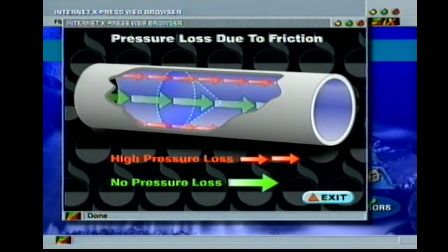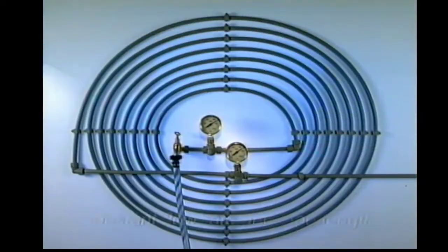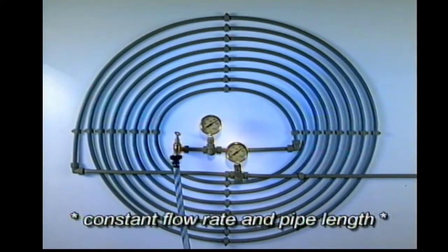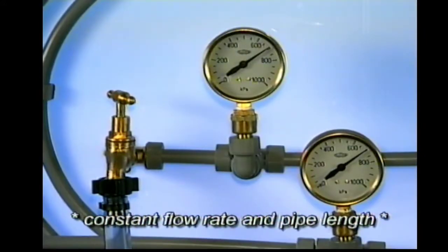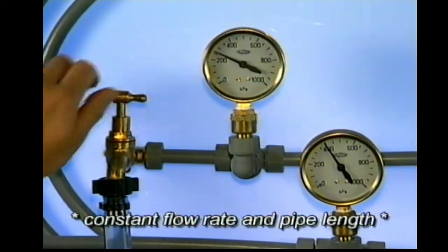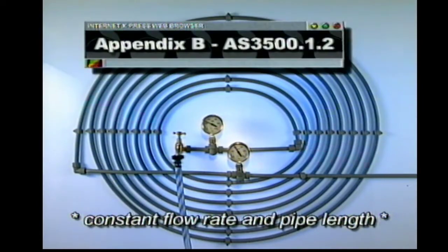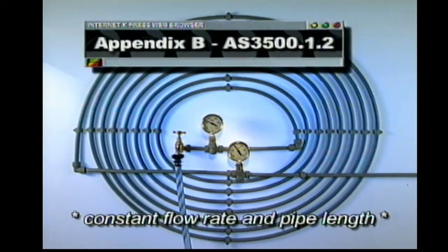So, how do we lose pressure? It's caused by the friction between the water and the pipe wall. There are two kinds of pressure involved: static, where there's no water flow, and dynamic, when the water's flowing. It's easy to calculate pressure loss using the formula in Appendix B of the standards.